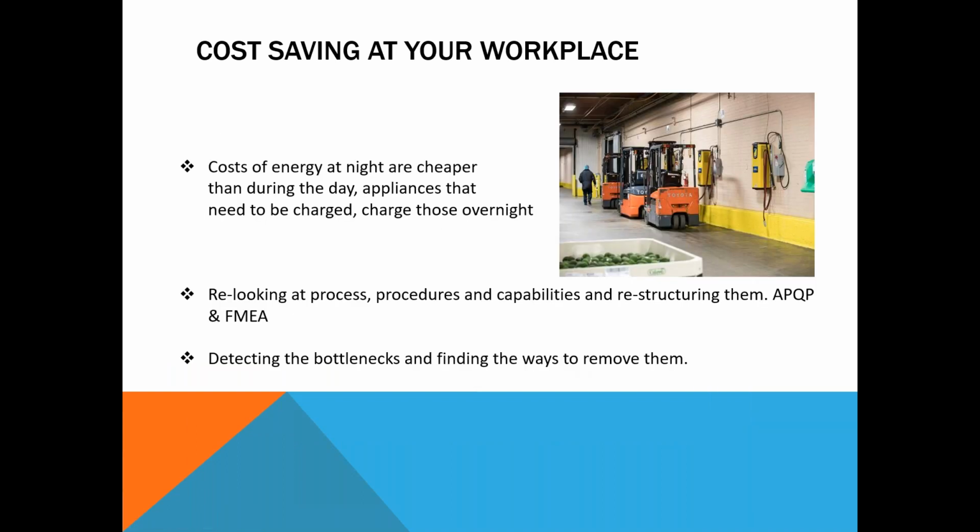If you see the cost, energy at night is cheaper than during the day. If you are paying 10 rupees a unit during the day, at night you are paying 1/3 of it. So you can see this is a charging station. You can see 6 forklifts can be charged. This is done in one of the companies. 6 stations we have made, and they are charging at night. You can see that fellow is putting a charger. Once it is charged, it will be taken off. But this is consuming 1/3 of the power that it would otherwise consume. These are the simple tricks where you can save a lot of money.